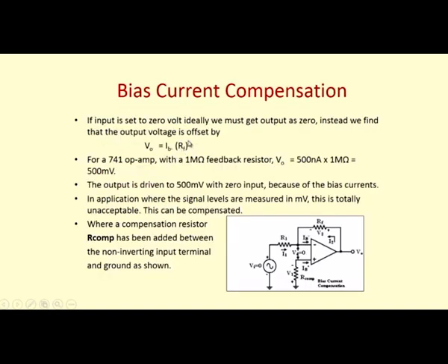So if the resistance RF is made small, then the output voltage due to the bias current will again be small, but we cannot make this RF small because it is the deciding factor of the gain of the amplifier. The input resistance must be more. We are always assuming the input resistance for an amplifier as 10 kilo ohms.